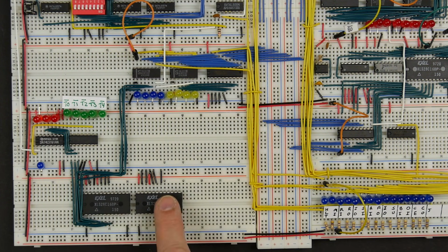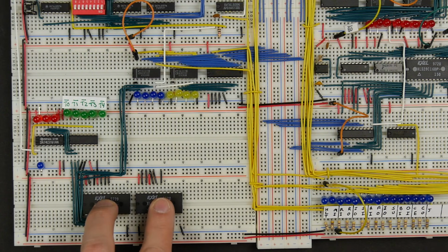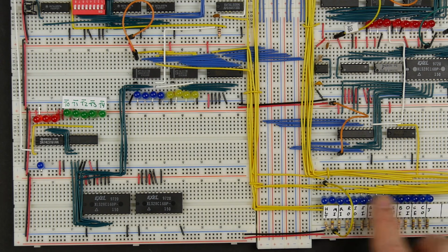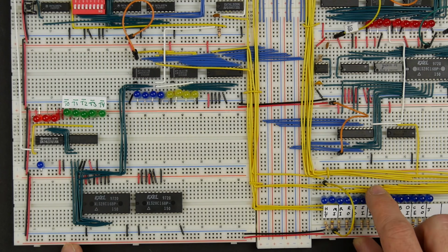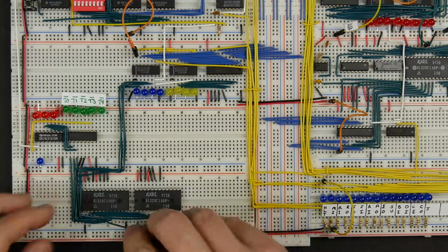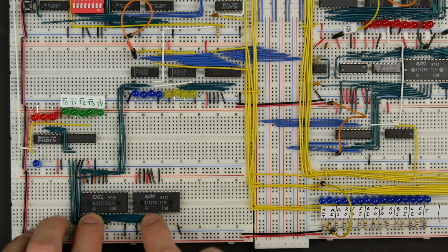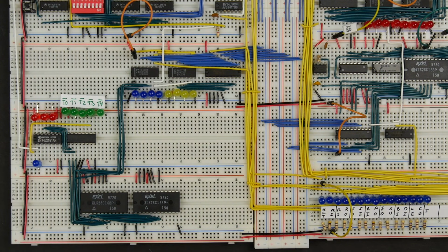And now as far as the second EEPROM, we want all the same address lines connected to it. So we just need to connect those exact same address lines in the exact same order over to the second EEPROM so that both of them will be pointed to the same address at the same time. And then we'll have 8 bits from this plus 8 bits from this, which will give us 16 bits that'll let us set whatever our control word needs to be. So we can just connect those 8 address lines straight across. There we go. It's a little bit tight in there, but hopefully that'll work. If not, we'll have something to troubleshoot.